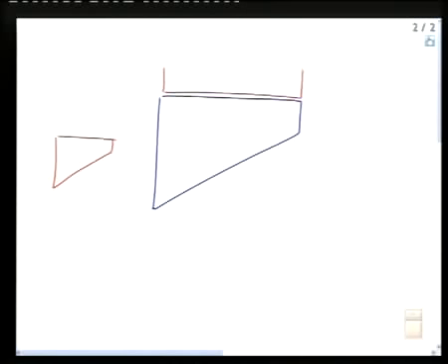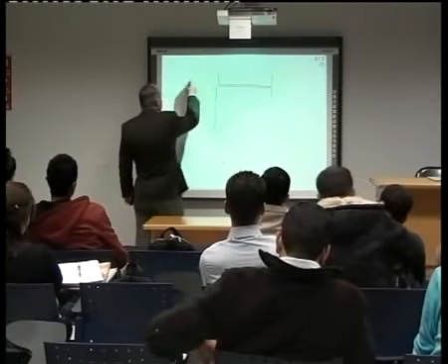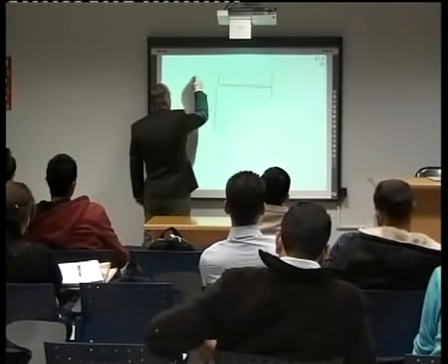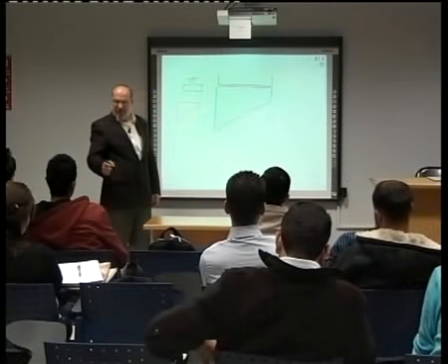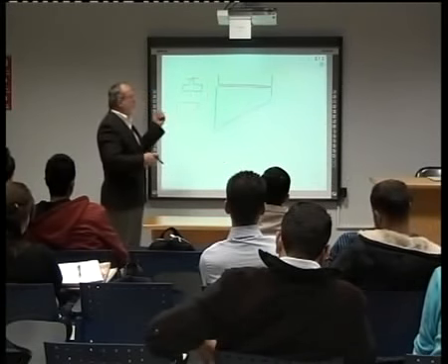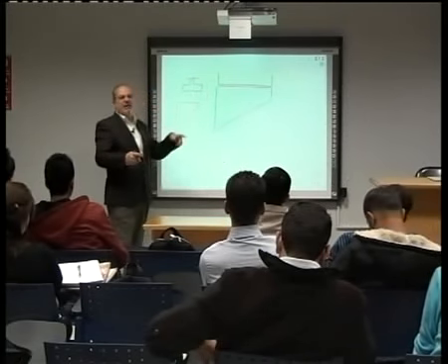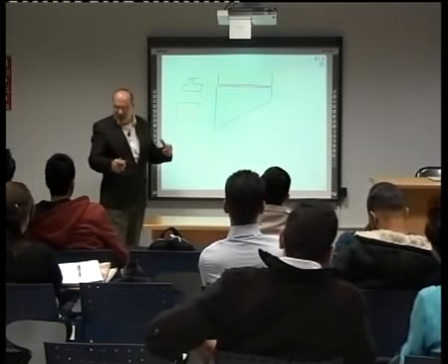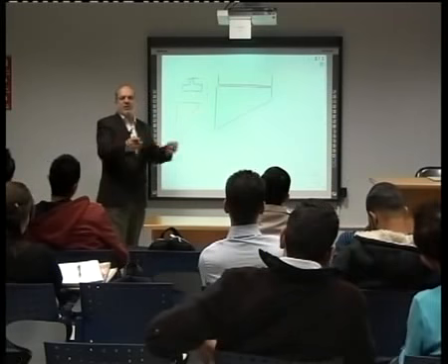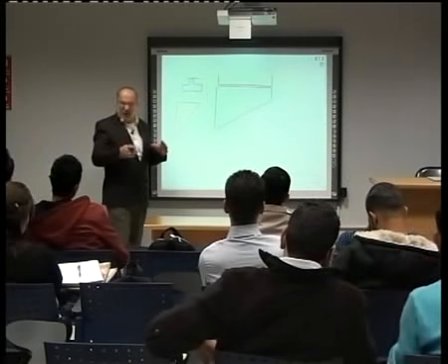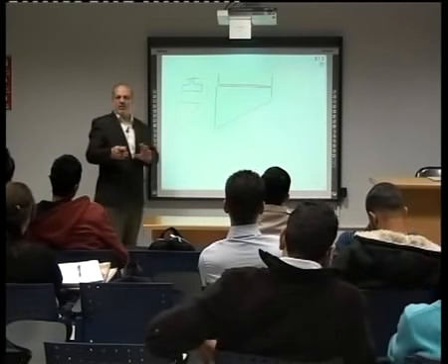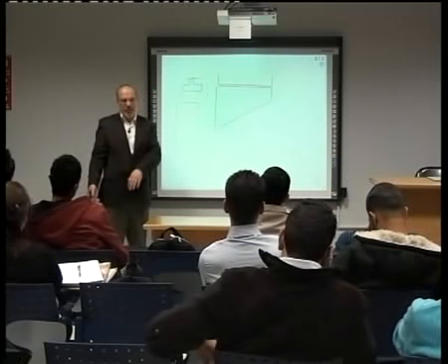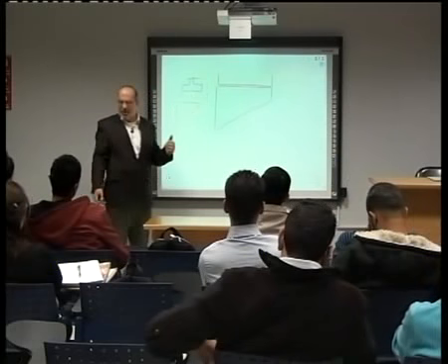For example, when we do a foundation, we draw the shear and moment, and we take the maximum moment to find the amount of steel. We always deal with the maximum, not with the minimum or the medium, because if the maximum is okay, then everything below it is okay. So we always take the maximum.